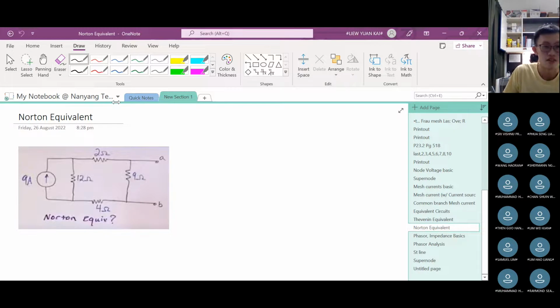Okay, here I ask you for the Norton equivalent, but if I ask you for the Thevenin equivalent, it's not a 1 minute away job, right? So let's go ahead and do that. So recap again. Anyone tell me in the chat, what's the number 1 step? Step 1 is find the open circuit voltage. Thank you, Samuel. Open circuit voltage. So let's go ahead and do that.